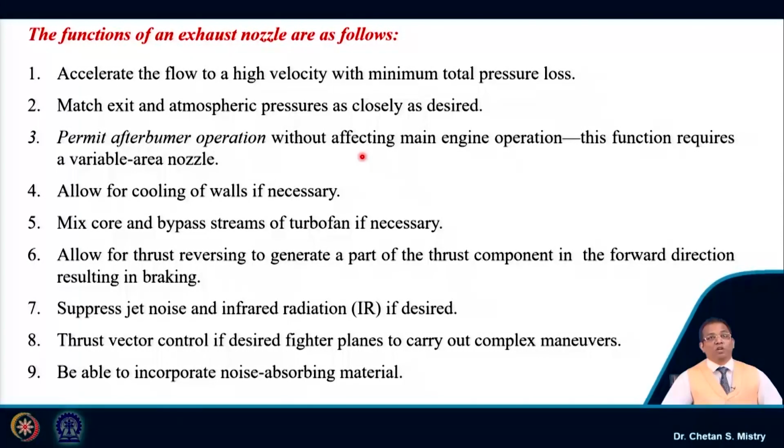It allows for the cooling of the walls if necessary, and mixes the core and bypass stream in the turbofan engine if necessary. So, in fighter planes, which have low bypass ratio engines, the flow gets mixed in the nozzle before it exits. Okay. It allows thrust reversing, as a part of the thrust component in the forward direction, and that will help in terms of braking.